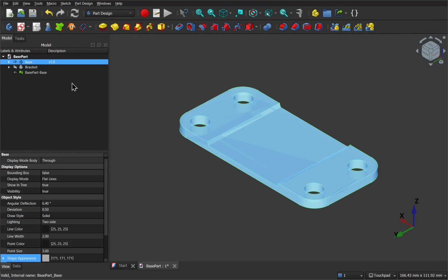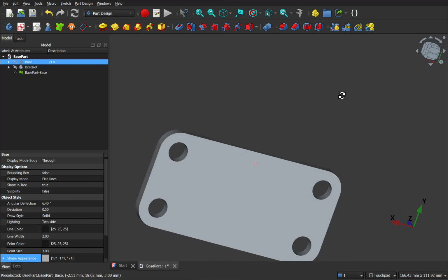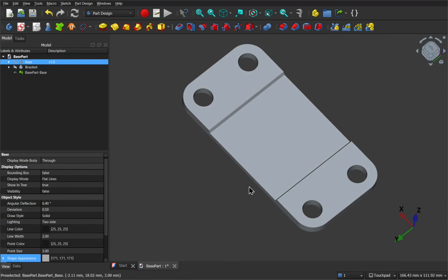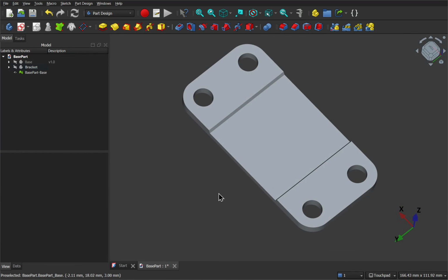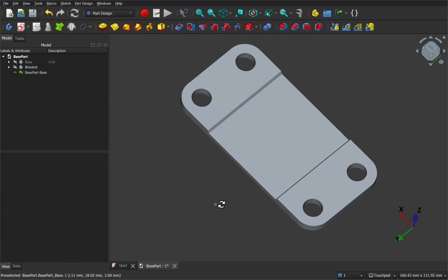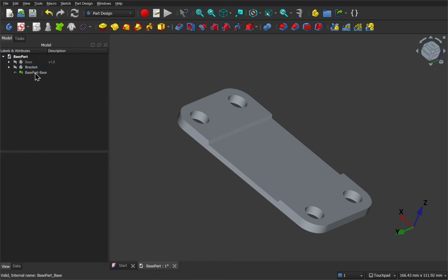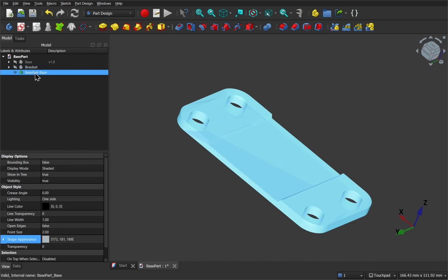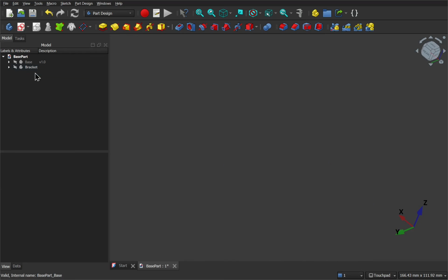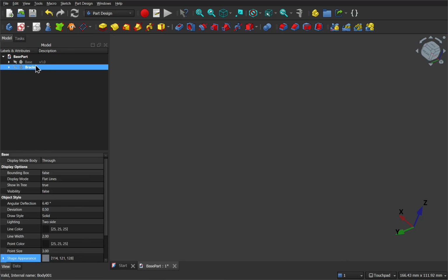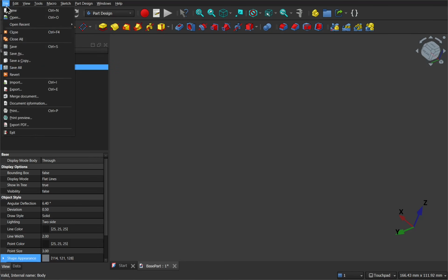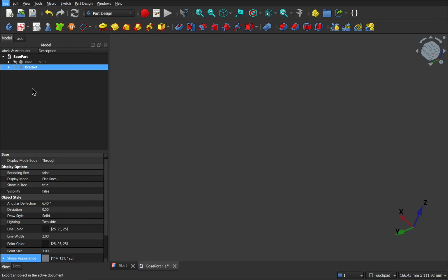Click on the base, body, and press the space bar. We can see the STL has been imported. We would import this to a slicer or another 3D program to use it in our application. Same process will apply to step. There's one thing to remember when exporting. Let's click on that STL, which is known as mesh, and delete it. We have a bracket in here as well. Even that's not visible, if I export that by coming up to File and come down to Export.